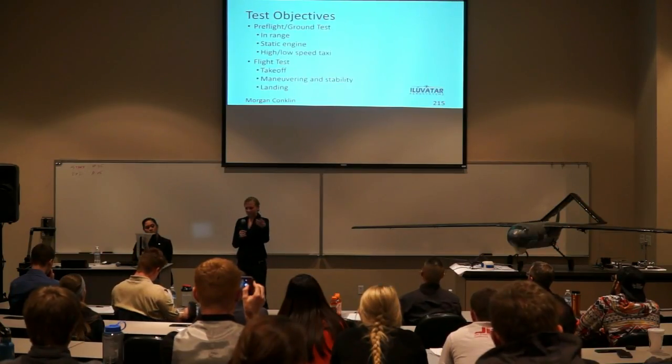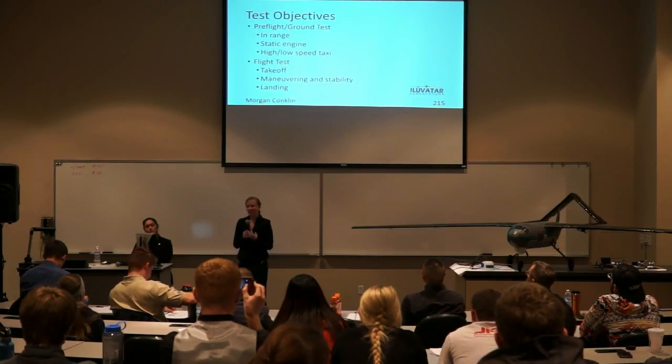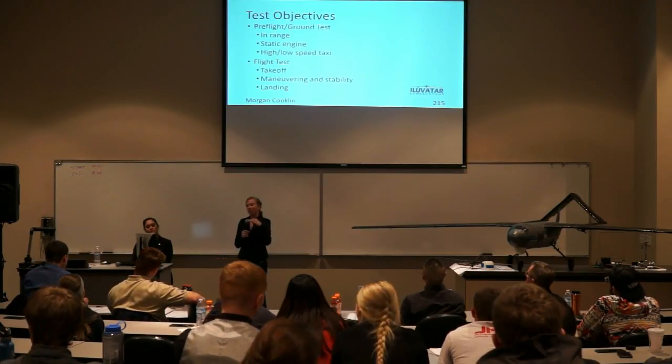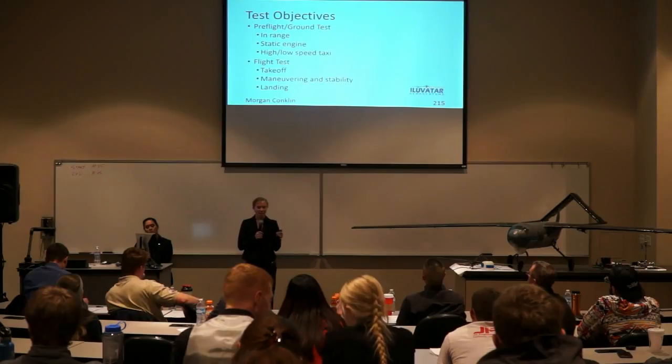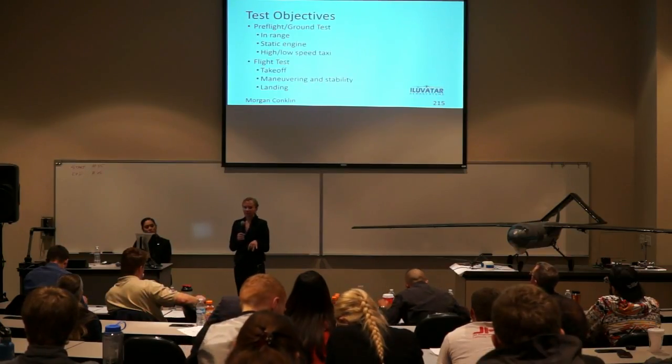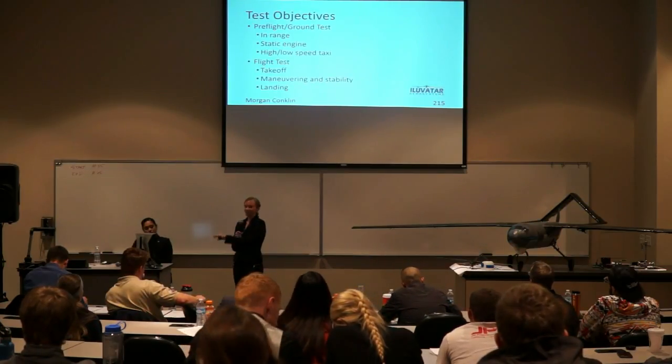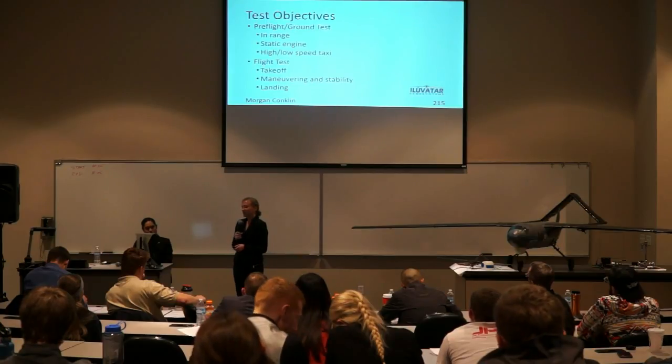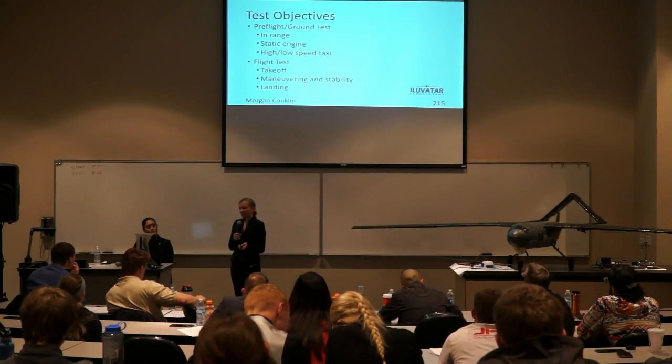For the objectives, we split it into ground and flight. So we went to do in-range, a static engine test, and high and low speed taxi. And that would be followed by a flight test if the ground test was successful. And then we did takeoff, maneuvering, and stability, as well as landing, which most people would say is a requirement after takeoff.